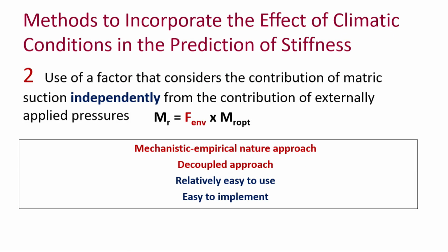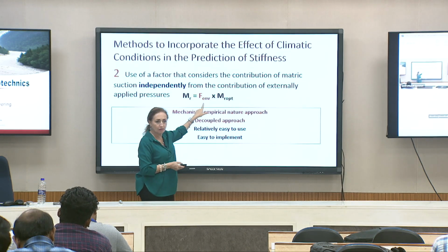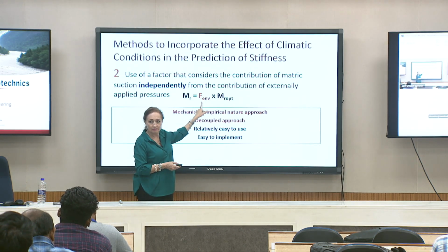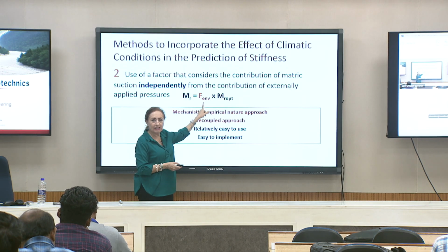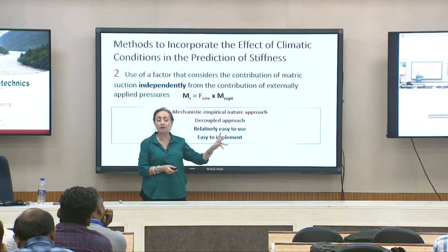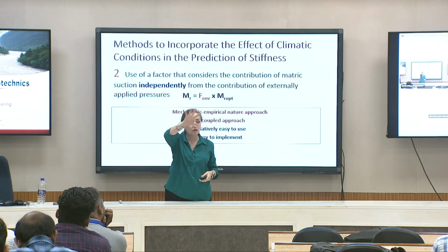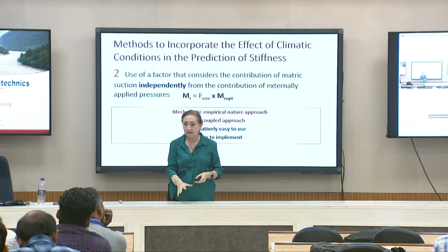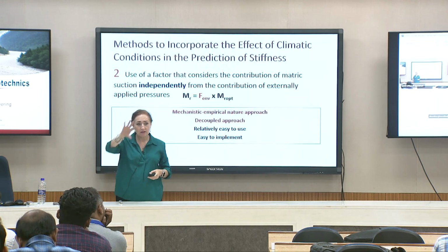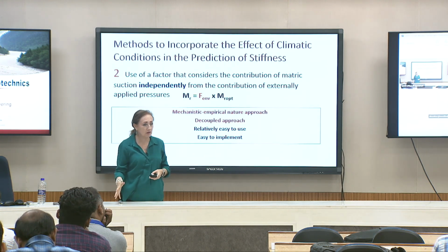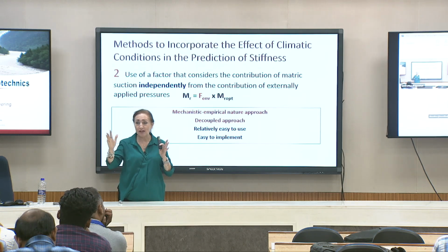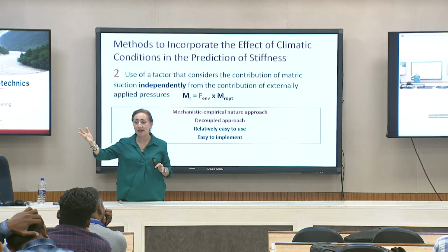And you saw this one that I got from Plaxis. But you didn't see how I got this one. The only thing you get from Plaxis are your suction profiles, which is going to give you those degree of saturation profiles, okay? And then I briefly showed you the equation to get the environmental factor, right?